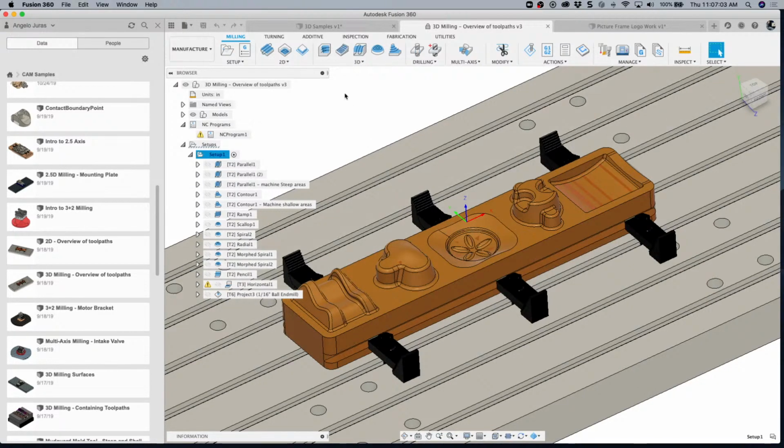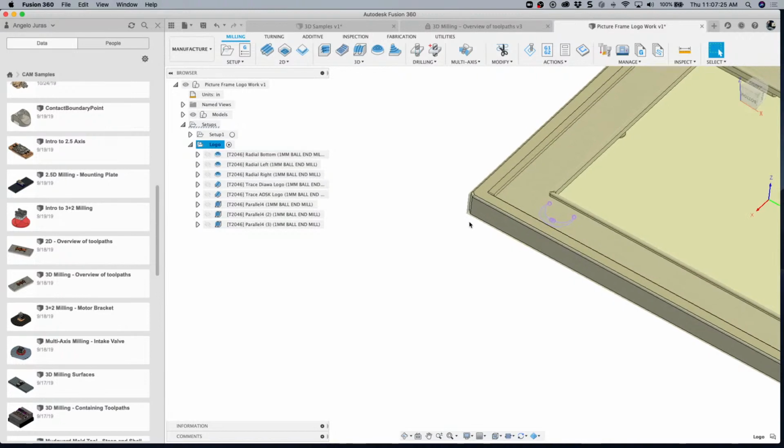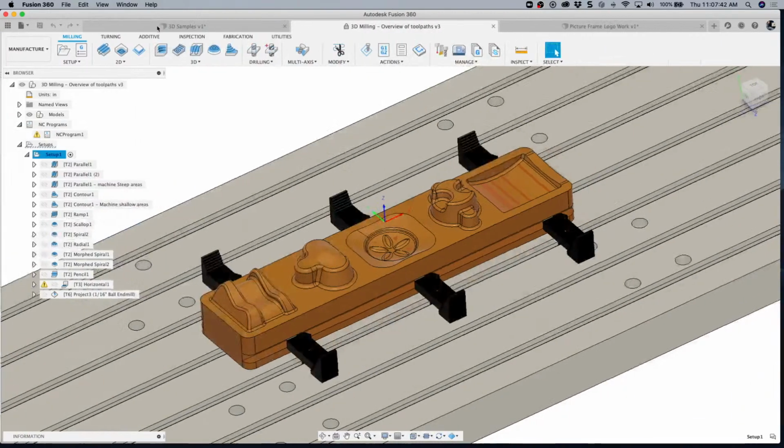And what I recommend is if you have a part and you're creating some toolpath, a lot of times what I'll do is I'll just recommend to people come in here, find something that works, that gives you something that you expect, and right mouse click and then copy it. And then you can go to navigate to your document. Let's say I've got another document here. And then you can paste it and utilize the same strategies, like all the settings. So that's a little pro tip that I like to use sometimes. So, okay, going back to this part. Let me close the data panel.